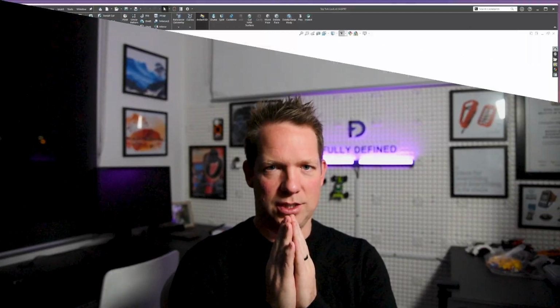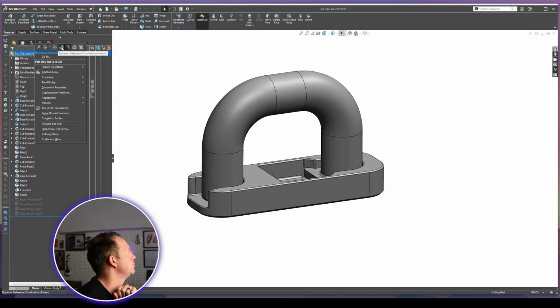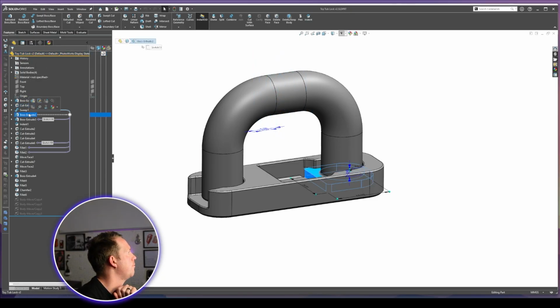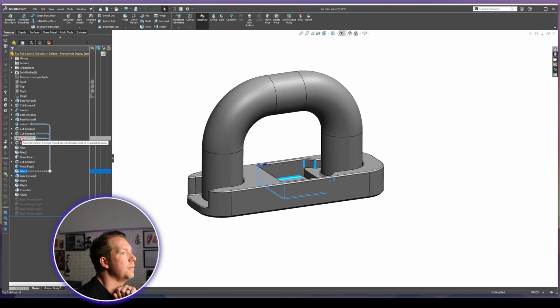In-context design is powerful, but it comes with hidden dependencies. These days, I avoid it where I can, but when I do use it, I know exactly what relationships I'm creating and how they'll behave if the design changes later. The same applies to parent-child dependencies. Once you understand how they work, you can design with confidence instead of fear. I've personally found that turning on the in-context relationships visualization tools in your feature tree is a huge help, particularly for a learner starting out.